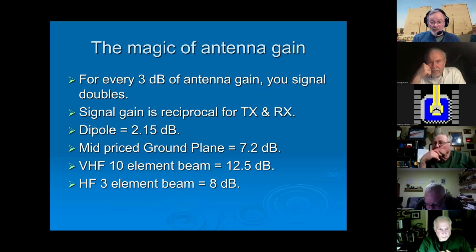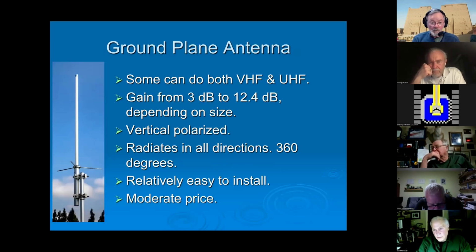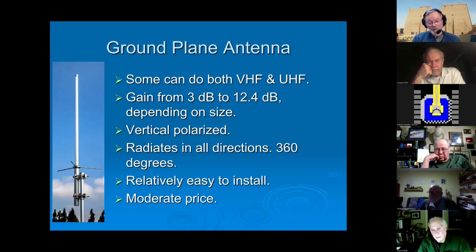So generally speaking, if you're just talking about a VHF, UHF antenna, like this guy right here, this guy is already pre-tuned for you. If you put in a chunk of pretty decent coax that has factory connectors on it, you're not going to have to work with SWR. You just don't really have to worry about it. If you try putting on your own connectors or crafting your own antenna, then you need to start probably thinking about SWR.